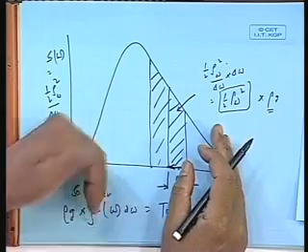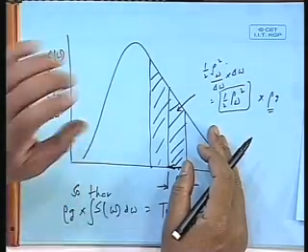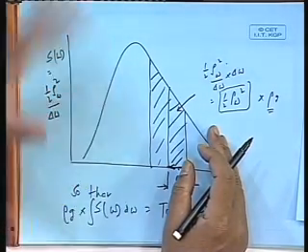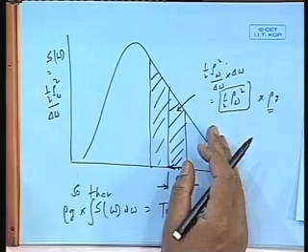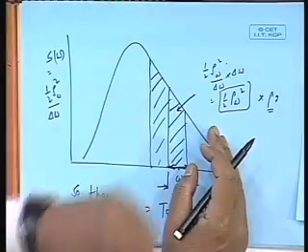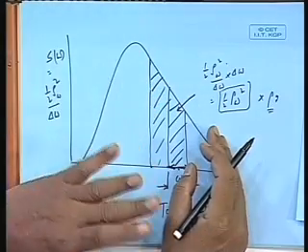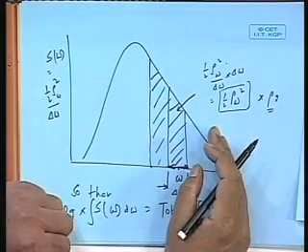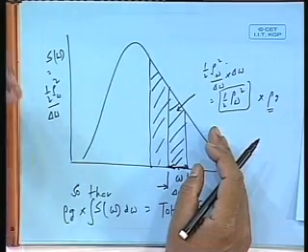Why is this area important? Because take this for example. The wind is blowing for long, say one full day. Now you took a record for 1 hour today evening, 5 to 6 o'clock. You got a record, so you broke it down to various components and you plotted this graph. He did that after evening, 9 to 10 o'clock. Now what he gets and what you get are totally different sets of amplitude and frequency, but the area under that should be the same because the total energy is constant. That is the basic philosophy.